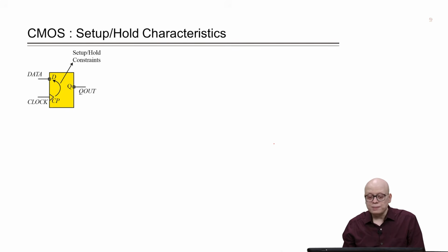Now, these setup and hold times are modeled inside our library. Why do we want to model this inside our library? Because these are attributes of the standard cells, for example, the flip flops, and setup and hold time can be measured only with the help of, say, SPICE simulations. So, only the one who is doing the library characterization can know what constraints should be imposed on the flip flop, so that the data is captured reliably.